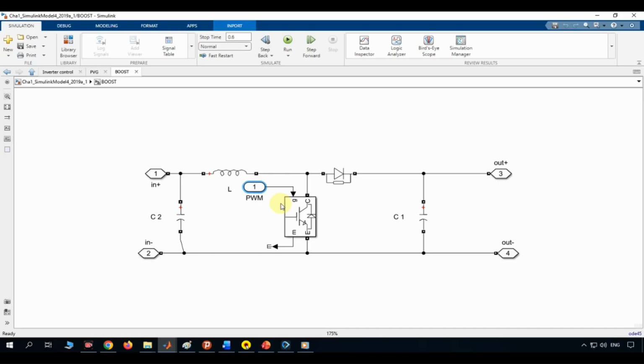When the PWM signal turns the switch on, it creates a direct path from the inductor down to the negative rail, essentially short-circuiting that point in the circuit to ground. When the PWM signal turns the switch off, that path is cut, and the inductor is forced to push its stored current somewhere else. That somewhere else is exactly where the boosting effect comes from, and we'll walk through that in detail in the next section.